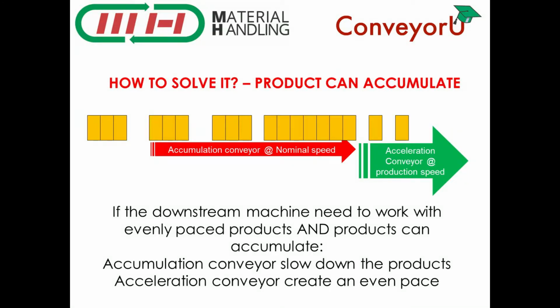Okay, the other situation, rather it is an easy one too, is that the product can accumulate. Okay, so as we said, regular shape, rigid product, and the machine downstream cannot load the product in accumulation. It doesn't have a minimum load. But in this case we can deal with this very easily. All we will need to do is to place yet again another accumulation conveyor running at the nominal speed.